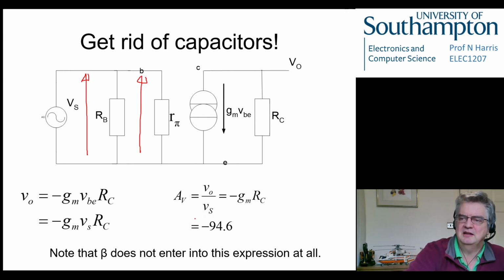Okay, so we've got a gain, a relationship of V out over VS, in this case of 94.6 under those operating conditions. So put in 1 volt, if you could put in 1 volt, you would get 94.6 volts out if your power supply was big enough. Okay, if your power supply is only 5 volts, which is in this case, you wouldn't get that out, you'd just get some horrible distortion. Likewise, put 1 microvolt in, you'll get 94.6 microvolts out, so it's about 100 times bigger.